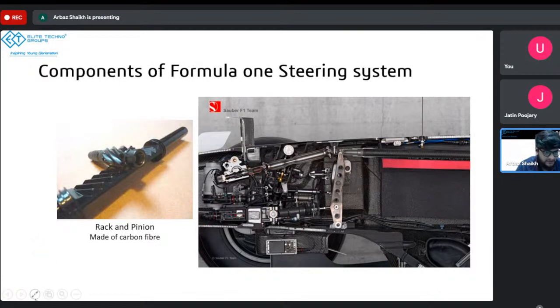Let me mark that one in red. So this is the first universal joint, and this is the second universal joint. Between these two universal joints, there's a motor. You can see this as the motor, and this motor is attached to the reduction gear, and this will help in reduction of your steering effort. Like we studied yesterday, the fully electric steering system. That's how this motor is going to help in rotation of this steering column. And this UJ is in turn connected to your steering column, which is going to be connected to your steering wheel. So the driver is connected with this column over here.